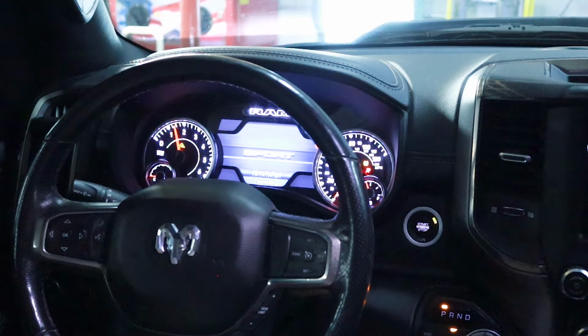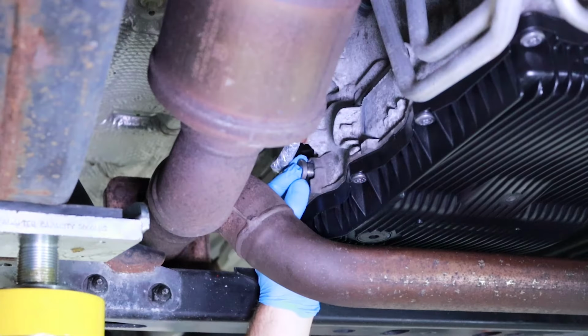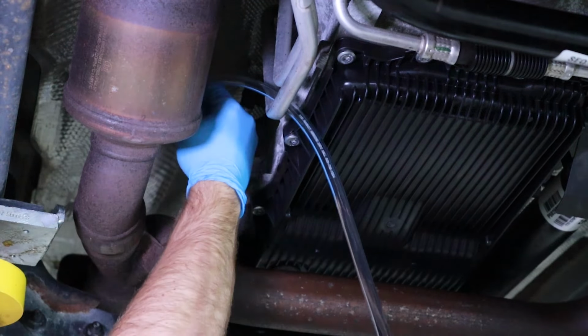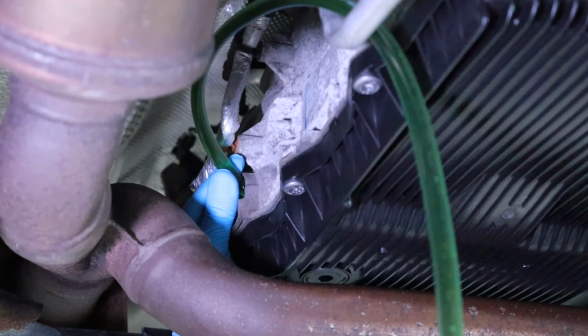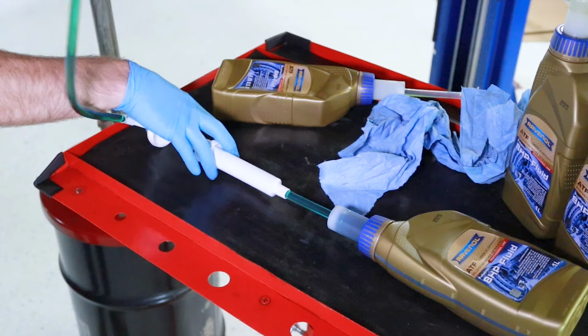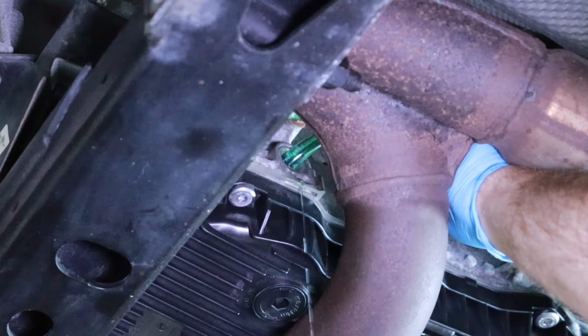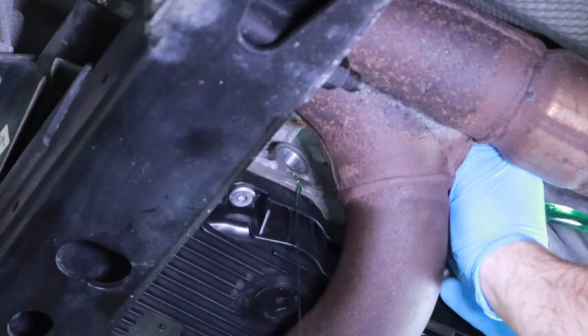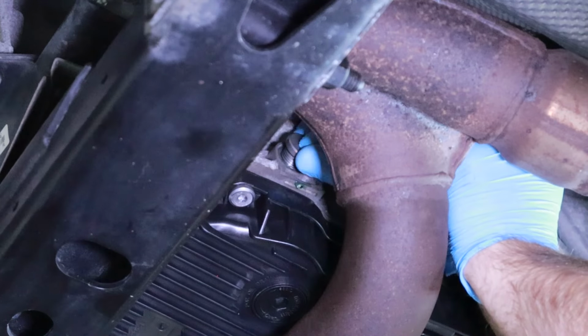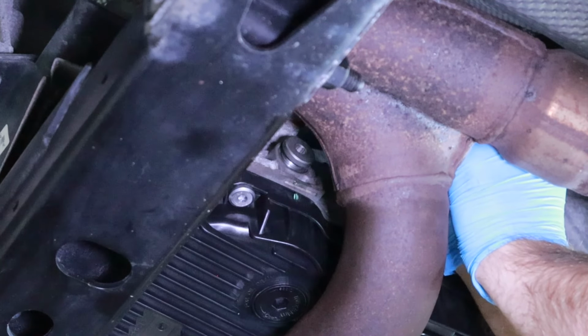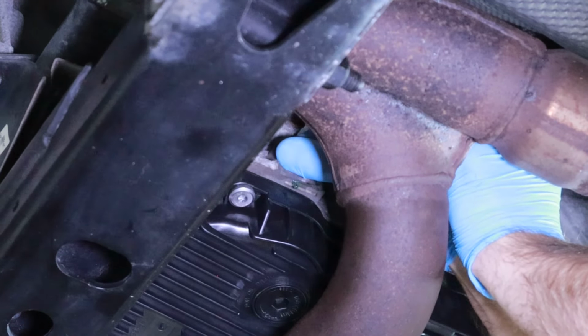This will allow the transmission to pump the new fluid you just added and distribute it throughout the transmission, resulting in a lower transmission fluid level in the pan. With the engine still idling, immediately remove the fill plug and again continue adding more transmission fluid through the fill port until a steady stream of fluid starts flowing out from the fill port. Once this is observed, you can reinstall the fill plug to a snug, hand-tight feel.